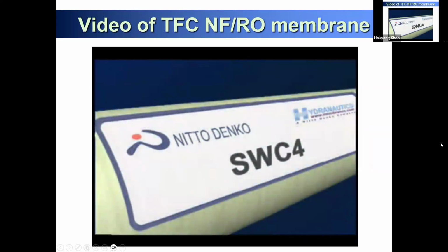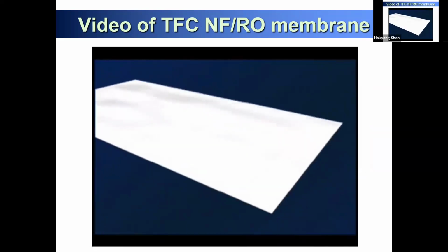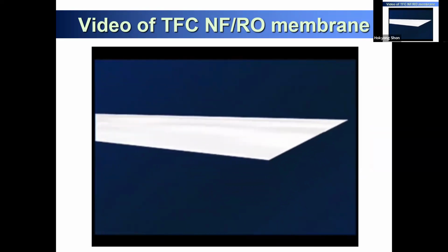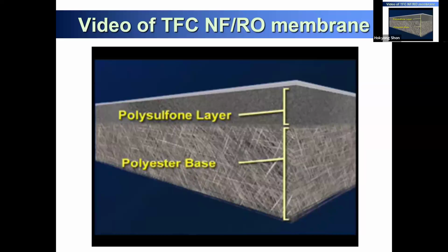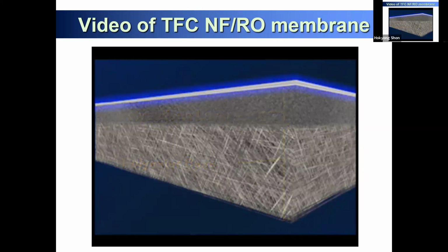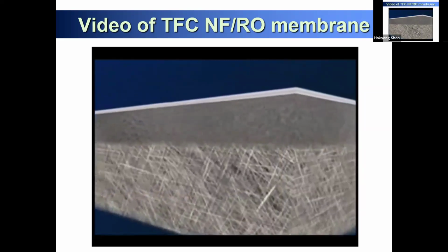To create our standard spiral wound membranes, we construct the flat sheet membrane using Hydronautics automated casting equipment. We begin the process with a fabric support base and then coat it with a microporous polysulfone layer. This provides additional support for the top 0.2 micron thick membrane barrier layer. This top barrier layer makes the actual separation to purify the water. The semi-permeable polyamide layer consists of a thin film of polymeric material, a few thousand angstroms thick, formed on a porous supporting material.